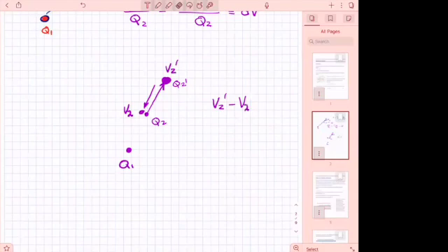I have a differential energy, a level of energy available. And that is called voltage in circuits. All right. So what do you say when you have a circuit, when you say I have a resistor and I have a voltage of like 2 volts across the resistor? The resistor is 50 ohms. What does that mean? That if I let it free, that is going to create a current automatically, because I have already accumulated energy on one side from the other, and therefore it is going to allow this flow to happen.